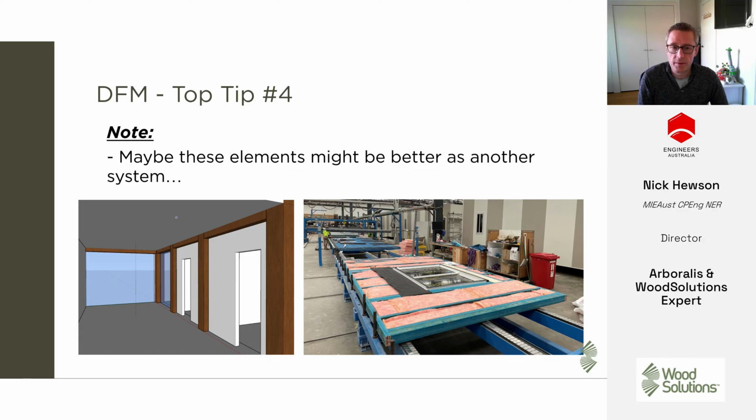If we want to use CLT, it works really, really well where it's a big solid panel with not too many openings in. The more holes and things you start to cut in it, the more effectively that panel costs per square meter. So where we can utilize that timber fiber in its most effective orientation and work it hardest is often going to be more cost effective.